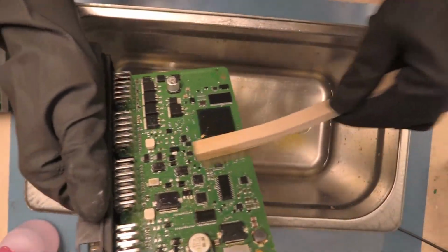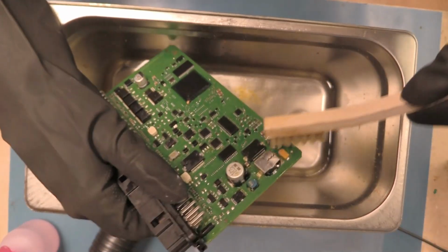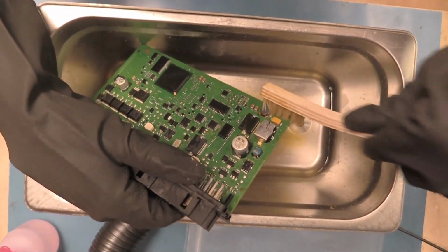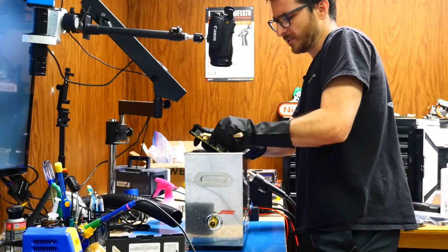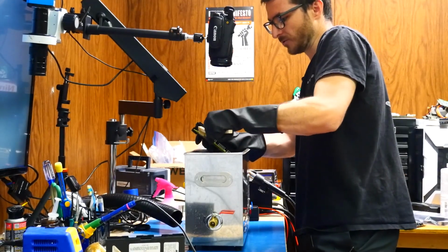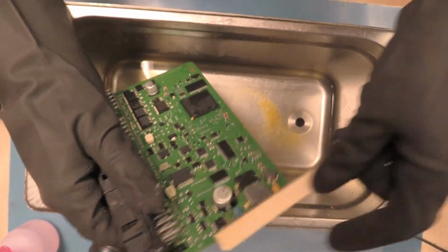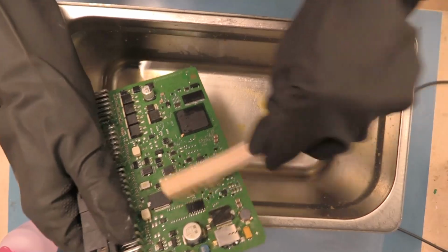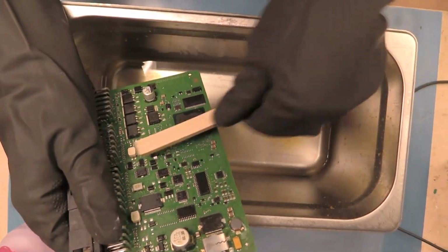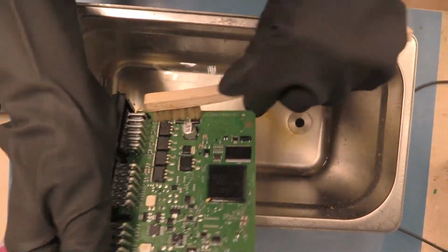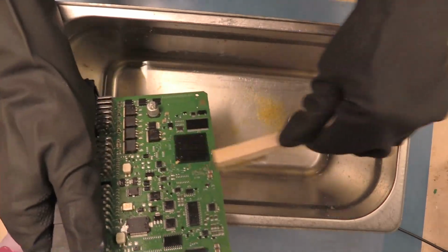Now, the important part for this cleaning is we want to make sure that all of our solder joints are no longer covered by the conformal coating. That's because in order for us to reball this processor chip, we're going to need to use our rework machine, which is going to heat this whole board to extremely high temperatures. When that happens, we're going to get some expansion on those solder balls, and if they're trapped under conformal coating, they're actually going to explode, and that could cause damage to the board. So the board doesn't technically need to be 100% cleaned, but we need to make sure that at least all of the solder joints are no longer covered.